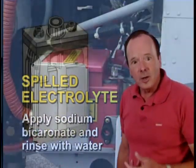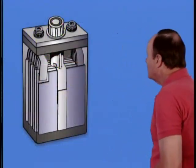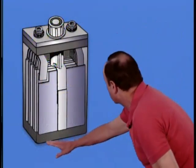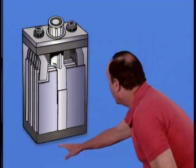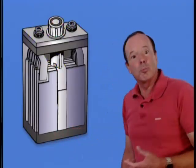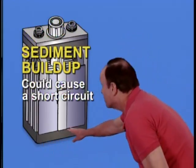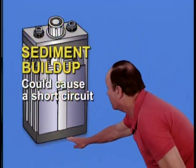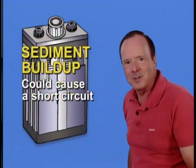Okay, now let's take a look at another problem with lead-acid batteries. Sometimes you have a sediment buildup at the bottom of a lead-acid battery. It builds up under the plates here in a cell container. And if that sediment builds up enough, it can contact these plates and cause a short circuit. So to prevent sediment buildup from contacting the plates and causing a short circuit, they provide lead-acid batteries with a space underneath the plates to hold that sediment buildup so it doesn't contact the plates.